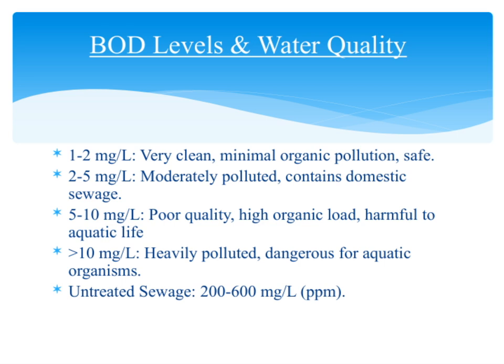To put this into perspective, untreated sewage often has BOD levels between 200 and 600 milligrams per liter, which is extremely high. This comparison highlights how much pollution can be present if sewage isn't properly treated, emphasizing the importance of wastewater management to protect our water resources. Understanding these BOD levels helps us gauge water health and the urgency of pollution control, all of which ties back to our overall goal of safeguarding water quality for ecosystems and human communities alike.